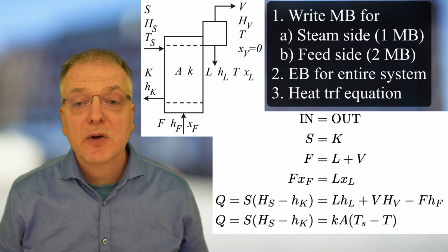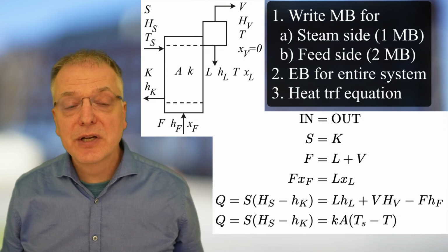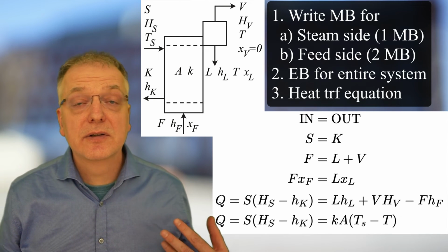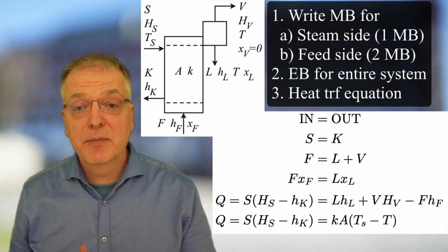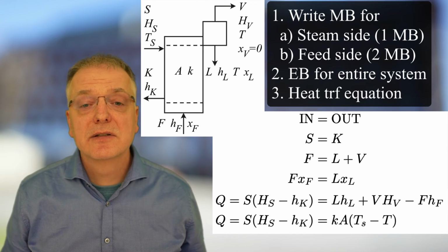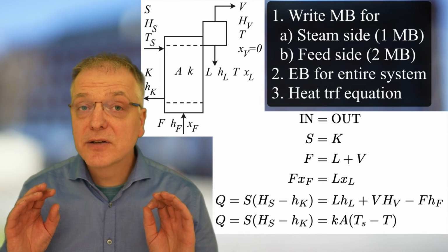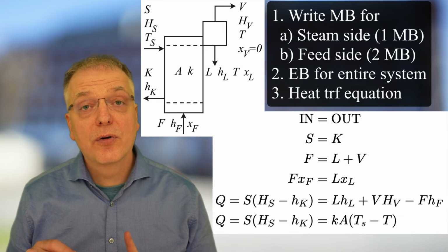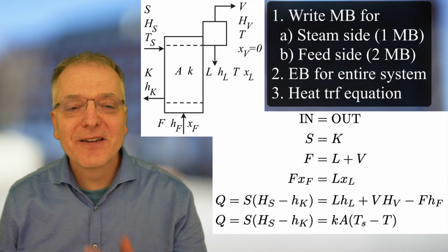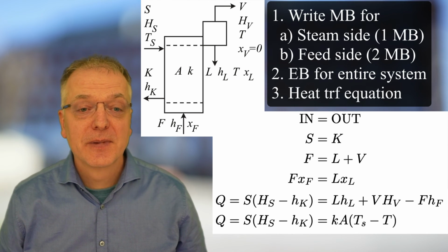transfer coefficient. What this means is that we have shifted from a problem in describing complicated variations in temperature difference and overall heat transfer coefficients along the heat exchanger to a simplified temperature difference and an apparent overall heat transfer coefficient that is rather difficult to estimate. In this course, however, we will typically either give you the value for the apparent overall heat transfer coefficient, or give you all other information you need so you can calculate it.